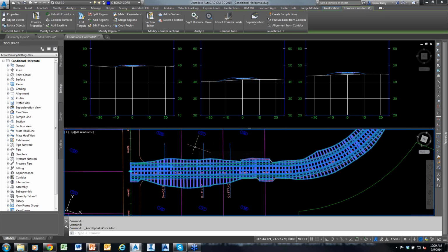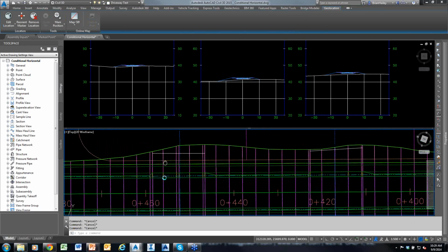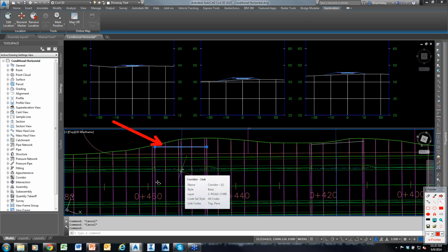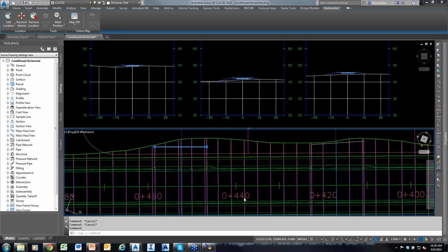There we go. And what we can see is where there's a polyline, it put in a driveway. Where there's not a polyline, there's no driveway. It doesn't do it at the polyline. It simply says, can I hit that thing? If I can, do this. Or if I can't, do that. That's all it does. The actual driveway, as you can see, is back here. I just have to be able to hit it within that 25 meters or whatever distance I told it.